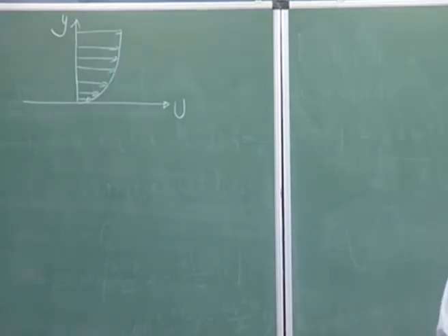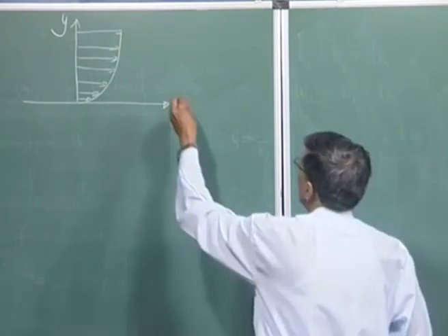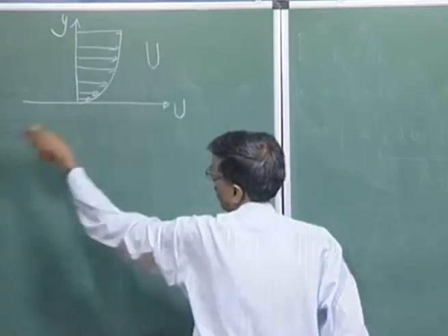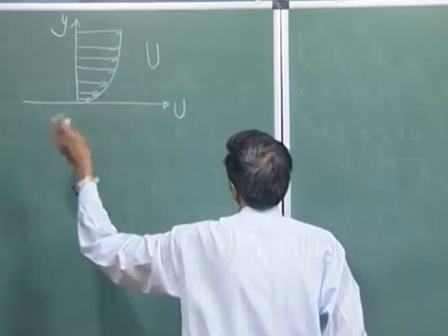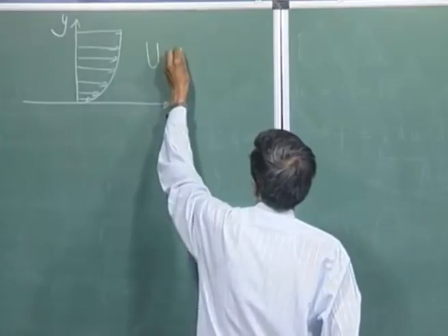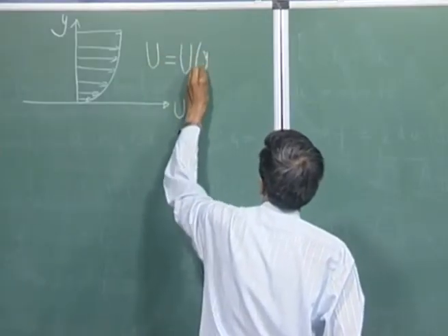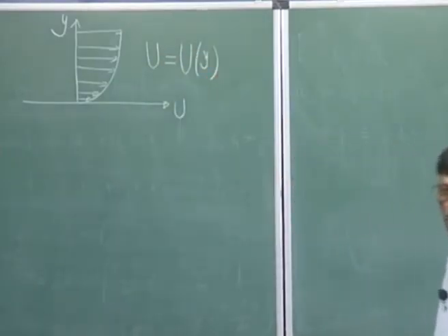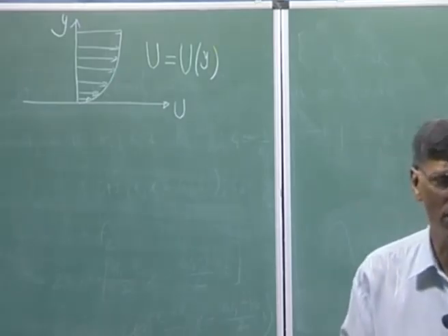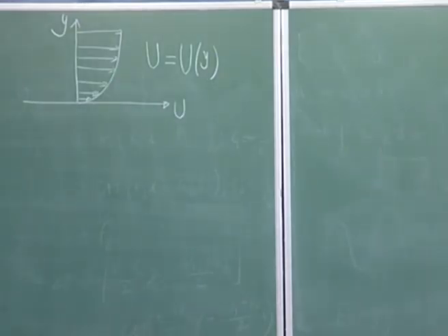We keep the lowercase notations for disturbance quantities. So what we have here is, of course, the mean flow. Earlier u2 was constant, u1 was constant, but here u is going to be u of y. So people were aware of it. Rayleigh, Helmholtz, Kelvin, they were all aware that the mean flow can have shear.